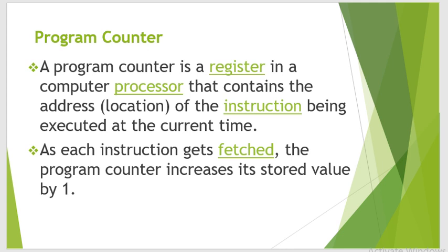Okay. Then the program counter starts at the zeroth value, from the first instruction. It holds the first instruction. While the CPU is going to run a program, the program counter gives the first instruction to the CPU register. Okay. After that, the program counter holds the address of the next instruction, and it fetches this instruction for executing in the CPU, and then the next instruction. Okay. Likewise, each and every instruction is going to be performed. Clear about it?